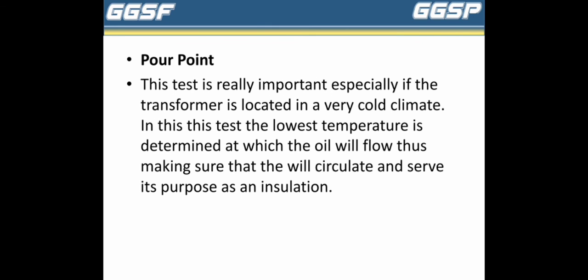Pour point. This test is really important, especially if the transformer is located in a very cold climate. In this test, the lowest temperature is determined at which the oil will flow. This makes sure that they will circulate and serve properly as insulation.